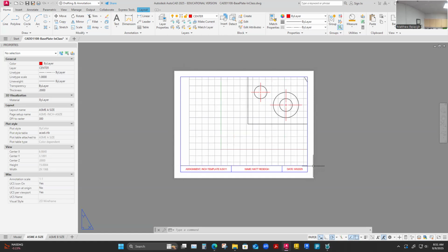Your viewports are really going to be sized to be the smallest to show that area of that model. And if I need more space on my drawing for another part, I have it. I don't have to have overlapping viewports necessarily. Anyway, we'll dive into that a little bit later, but I want to jump into the viewport here.